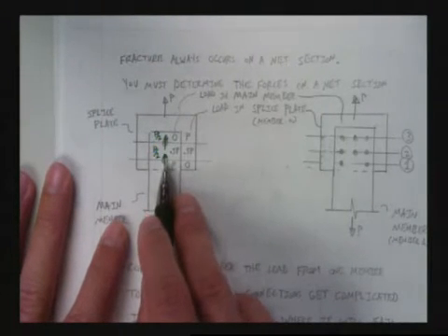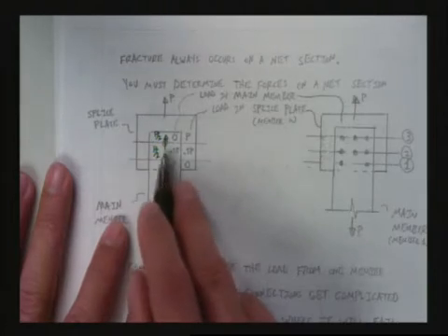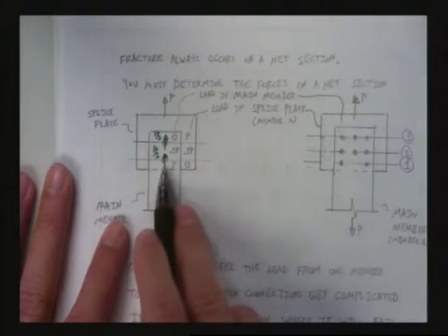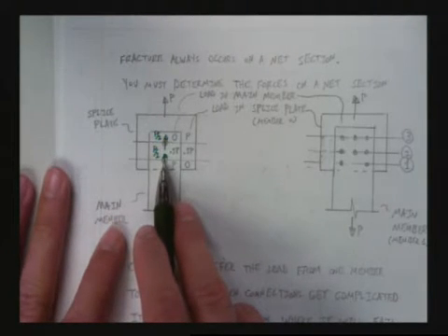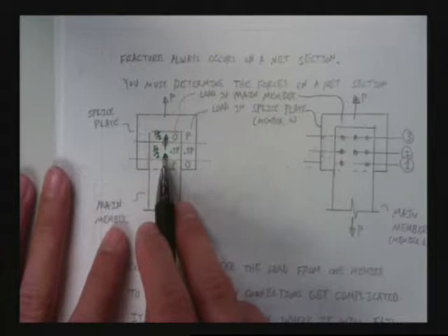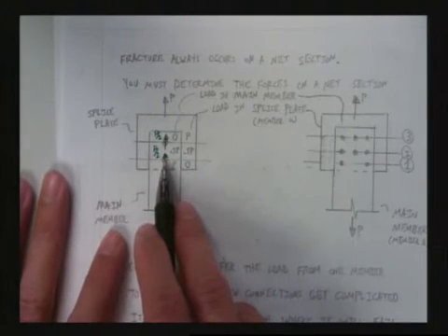But that only happens when things like you have slotted holes, where you have bolts that may be flying around in the holes. And in that case, they make you use pretension bolts. At that point, you're not actually relying on the shank of the bolt to transfer the load. You're relying on the friction on the surfaces to transfer the load. So it can be done. It's a little bit different system.